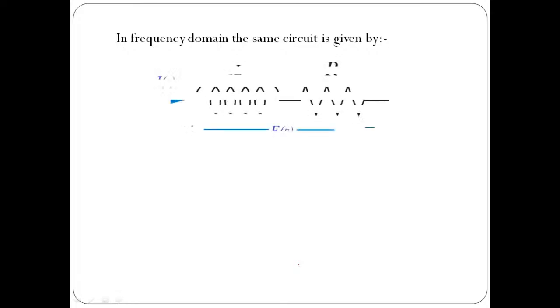We convert the given system into its equivalent frequency domain. And this is possible by applying the concept of what? Laplace transform. So here you should know the basic fundamental conversions of RLC circuits, if they are available in time domain, how we can represent them in frequency domain.